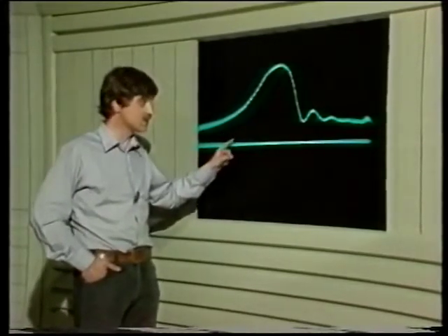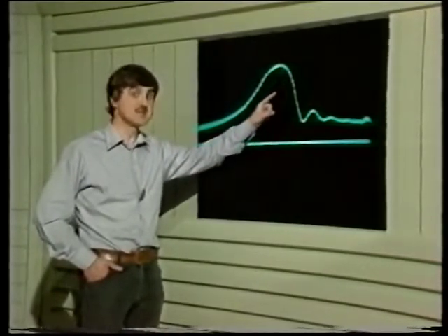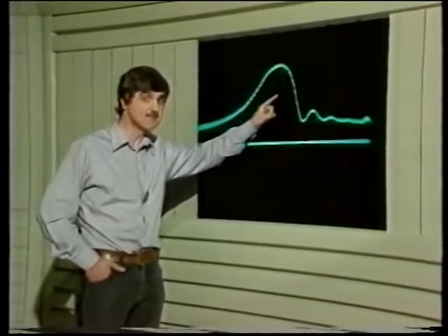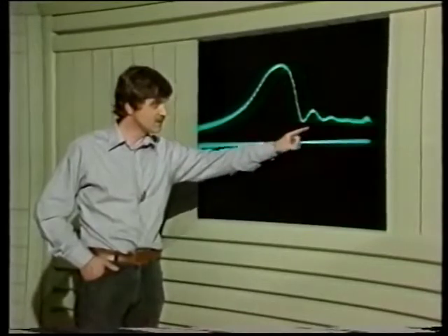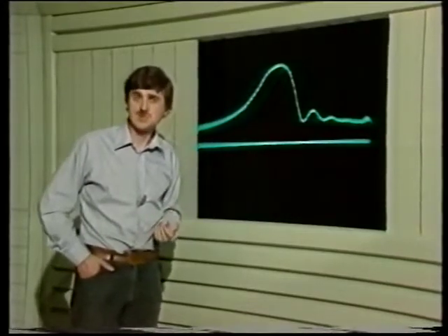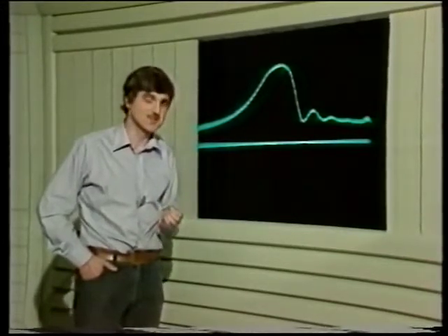For example, for our experimental setup, the transmissibility at low frequencies is about 1, rising to a maximum value of about 6 at the resonant peak. And then, at high frequencies, the transmissibility drops off down to 1 and below 1. So, with this information, we're in a better position to make adjustments to the spring, mass, damper characteristics of a vibrating system in order to avoid those damaging oscillations at resonance.